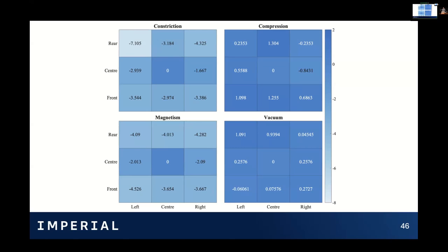So this isn't something I've had an opportunity to experiment with myself. I have had some questions in the past about particle size and how that affects particularly the hardness change. My hypothesis, I suppose, if I were to be able to do this experiment, would be that smaller particles would jam together and brace a lot better because you could have more contact points in a given volume. But then actually for transferring the vibrations, you would want larger particles because you then need more interfaces for the vibrations to actually propagate through to get to your user at the end.